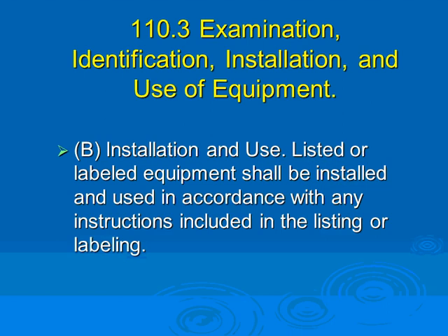GFCI receptacles in an accessible location. Did you guys hear about that one? It has to be in an accessible location as of 2011. Right? Accessible location. So take this scenario. Now, if you have a GFCI, and if you look where the GFCI accessible location is located, if you have a GFCI that is powering a vending machine, does it have to be in an accessible location?